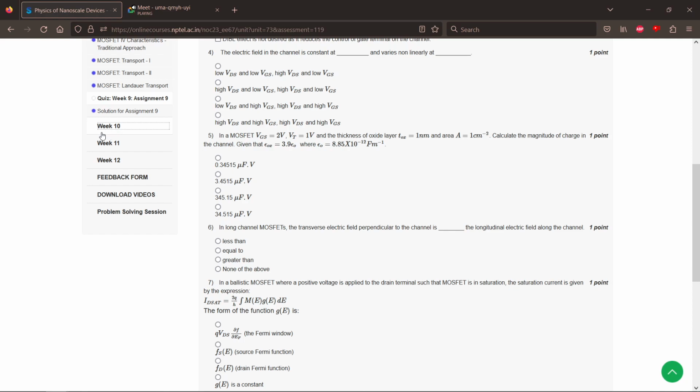There, ballistic transport models will no longer be applicable for the most straightforward reason that the channel will now contain maybe a few dozen atoms. At 5 nanometer, the channel will contain maybe 30 atoms. So when there are only 30 atoms, I cannot talk about that system in terms of conductivity, or resistance, or even current for that matter. I have to treat it as some kind of a potential barrier, look at the transmission coefficient, and treat it as a tunneling problem.